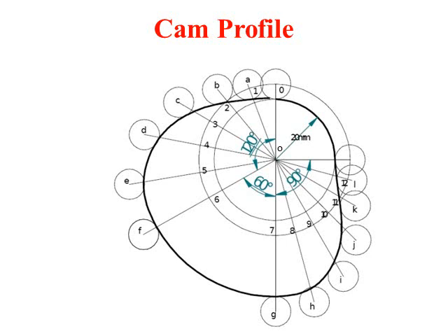Next, we have to divide the prime circle. That means we have to transfer the outstroke and the return stroke onto the prime circle. So now taking O and 0 as the base, draw the outstroke, that is 120 degrees, and again the return stroke, that is 90 degrees.